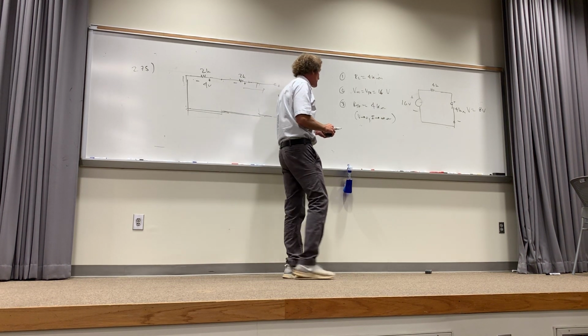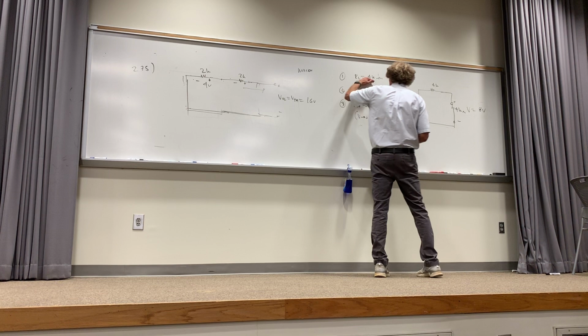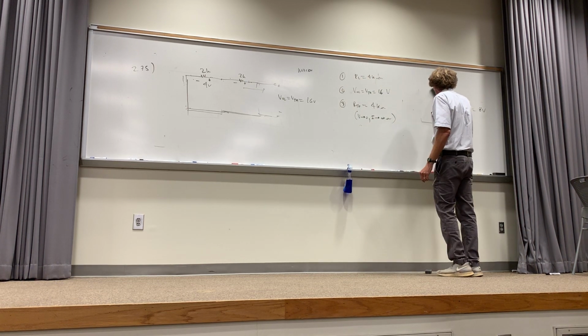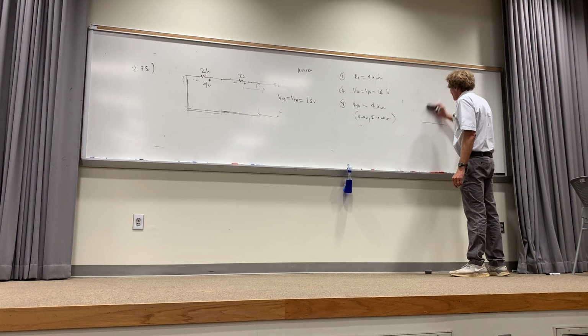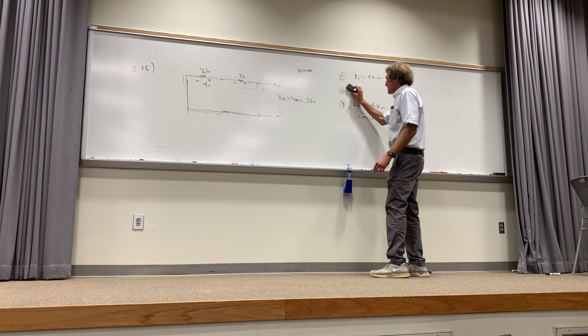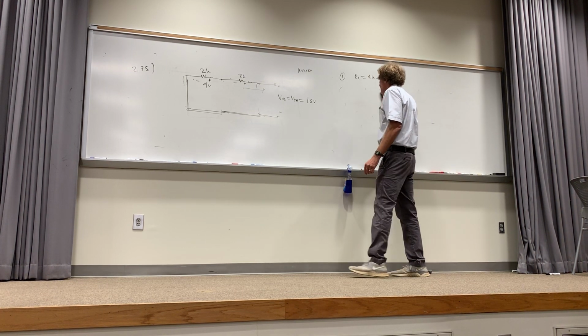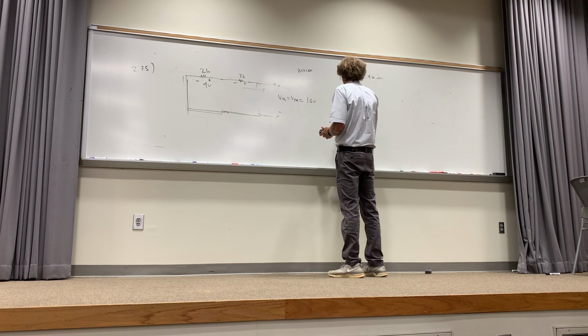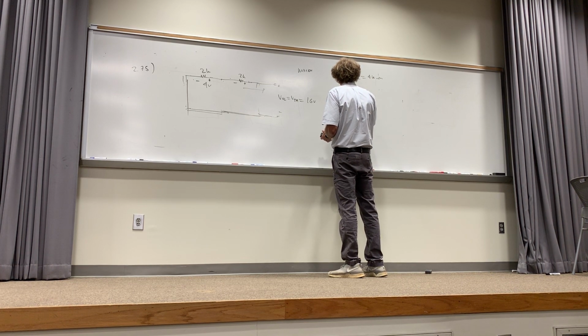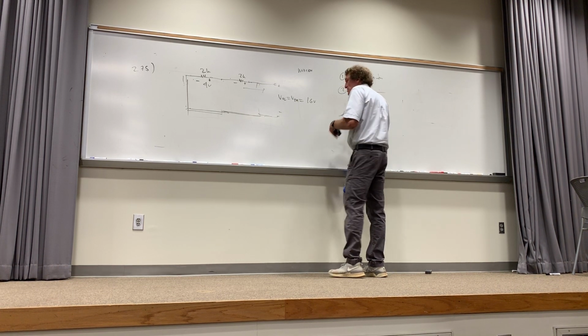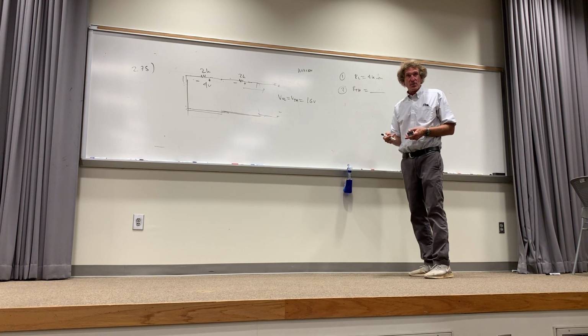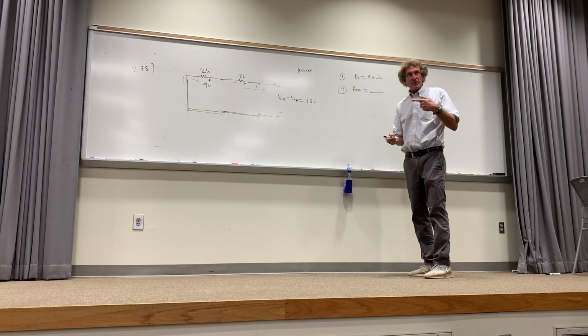For Norton's analysis, we do this step, but the difference is the very next step. We first identify the load and we remove it. Then, what happens is this. You could say second thing is find R Thevenin. Then you find R Thevenin just the way we've done in the past, all right? We turn off the sources, got me? But here's the thing that's a little bit different.